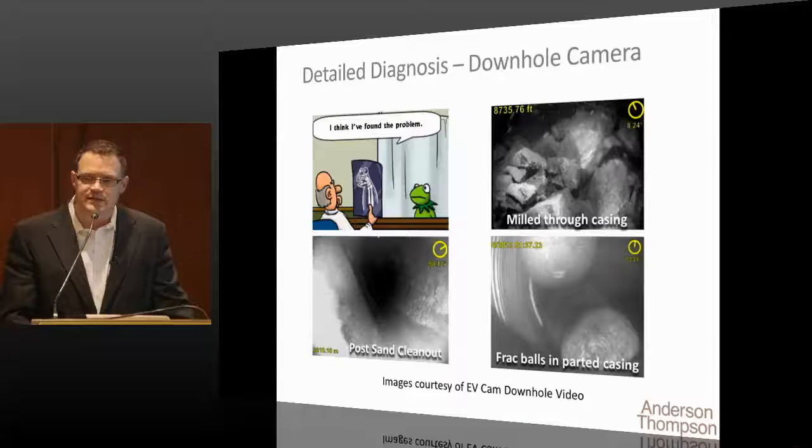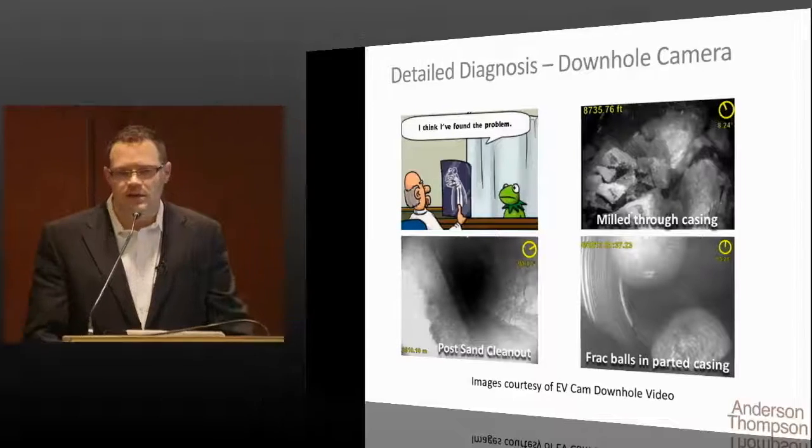But if we see this in the RTA, if you diagnose a number of candidates where this is a problem, that would be your candidate list that you might want to go back and maybe run a camera, diagnose the issue, because this is low-hanging fruit if we can do a clean out to solve a problem or do a very cost-effective workover. The potential of upside in terms of accelerating reserve recovery or even changing EURs can be done